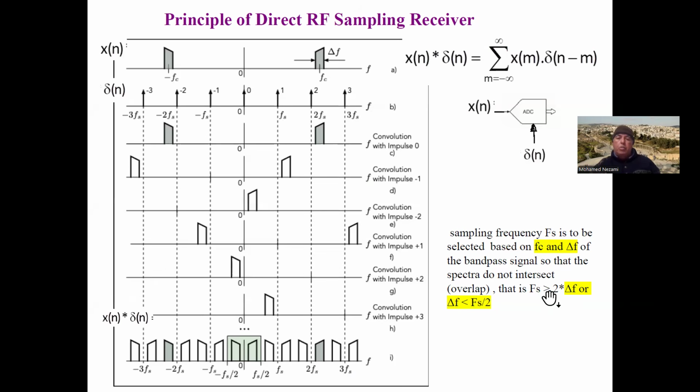And that's the Nyquist condition, which says that the sampling frequency has to be at least twice delta F, and it has nothing to do with the carrier. So the carrier can be at 28 gigahertz, but the sampling frequency doesn't have to be that. All it has to be is more than twice the bandwidth. If the bandwidth of your information is 28 gigahertz plus or minus 100 megahertz, so 200 megahertz of information bandwidth, your modulations, then all you need to do is sample at a frequency higher than 200 megahertz, and you'll be able to cover these, just as an example.